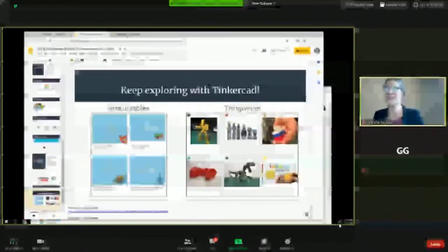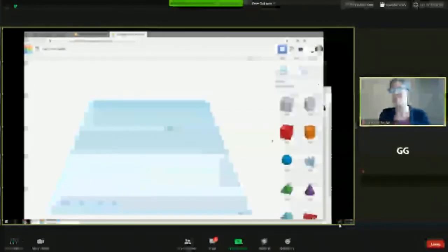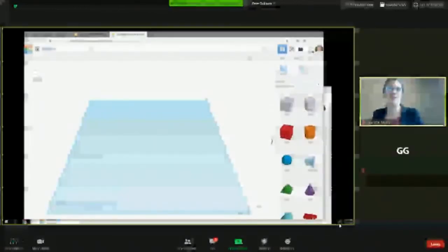As I mentioned, we're going to do 3D design. That's the default that Tinkercad opens in. When you want to create a new design, you simply create a new design. It gives it a funky name once it generates it, and to change that, I'll give you a quick interface tour of what's on the screen. As you can see, really interesting name. You just click on it, and we can rename it to Keychain Project. That's the icon I mentioned for getting back to the homepage.